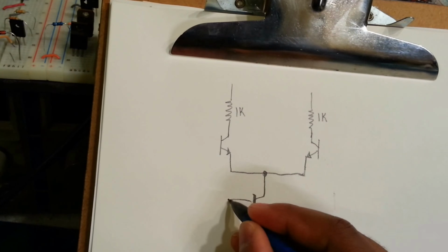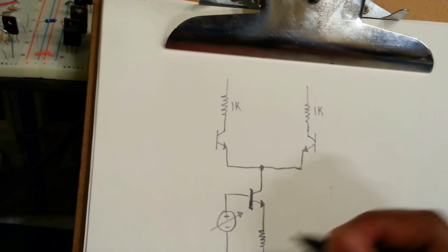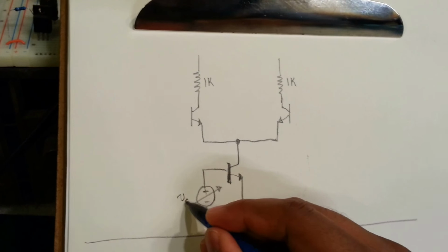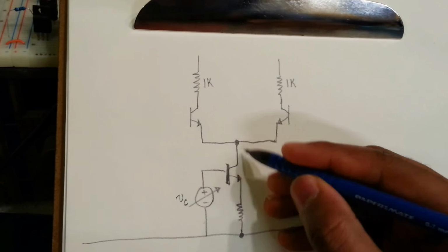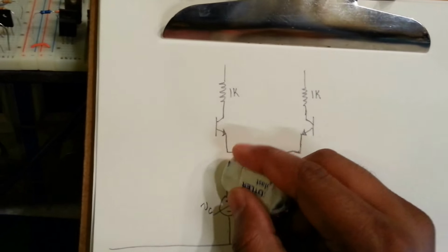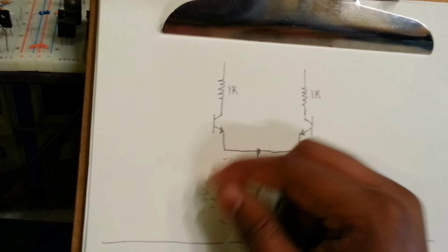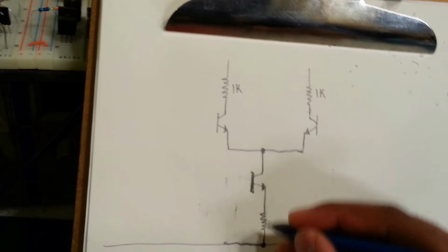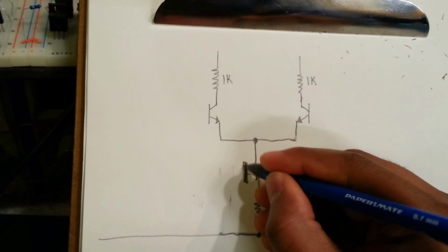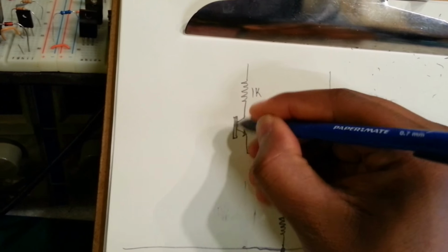And we're told to use, as I mentioned here, an externally applied voltage source to control, so if we call this VC, to control the current flow through this transistor. But like I showed you on my final circuit, I'm not going to use this for ease of minimization, because in circuit design you're always trying to minimize the amount of voltage sources that your circuit uses. So what I'll do is I will only use voltages that are already present in the circuit.